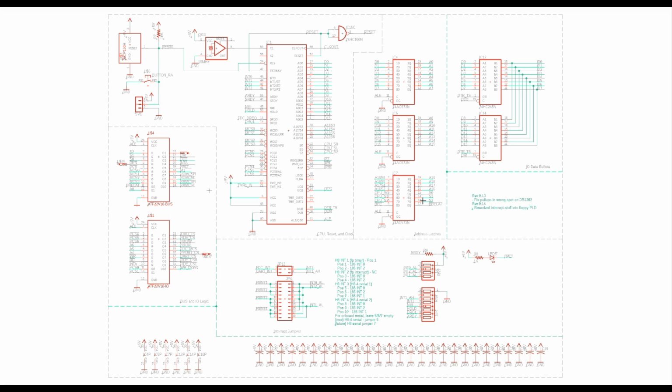Because most of our I/O devices are 8 bits, that's what these bus transceivers here are for. Now, one option is you could simply use only even addresses. If you use only even addresses, then only D0 through D7 are used. You'll never use the odd ones that are up here, D8 through D15. But that is really inconvenient because a lot of software is designed to use consecutive addresses in a device and is not designed to use only the even addresses.